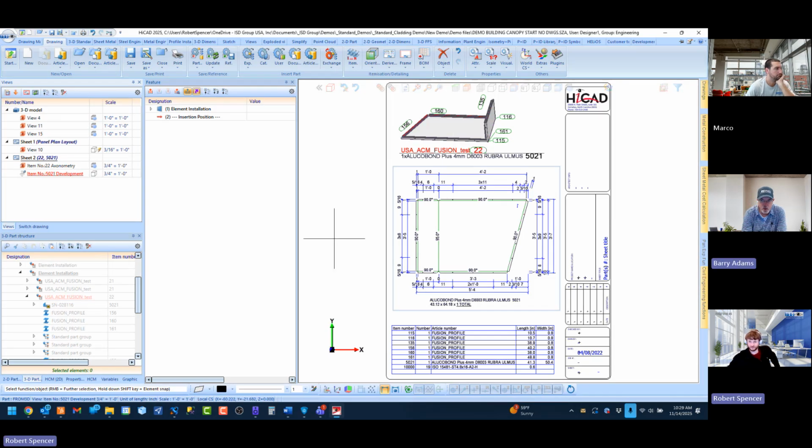So would there be a workaround to still do something like that, maybe not on a super automated basis? You can definitely create this, and it wouldn't be that hard to create one at a time. You simply isolate a view with your panel on it. You flip it over. You do auto annotation. You activate your profiles and the structure. You say auto annotate. Boom.